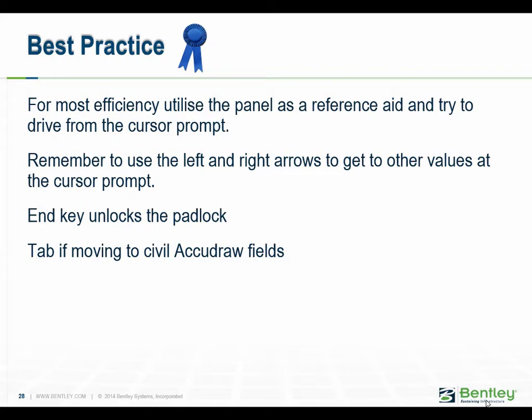What I would suggest will happen is that as you become more experienced, you'll be starting to use those cursor prompts much more. But remember that you've got left and right and up and down on the cursor prompt to allow you to navigate through what's on the panel, unlocking values and entering new values. And if you are integrating with Civil AccuDraw to try and build up additional relationships, just remember that when you activate AccuDraw, you can use the tab key to move between the fields.